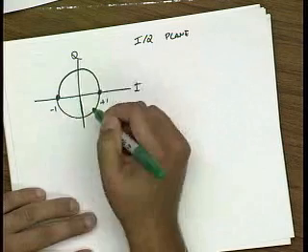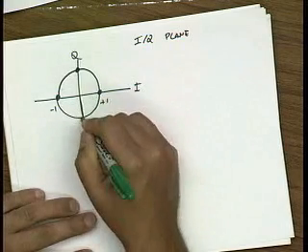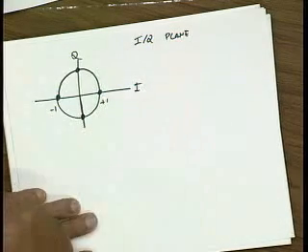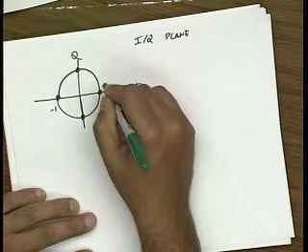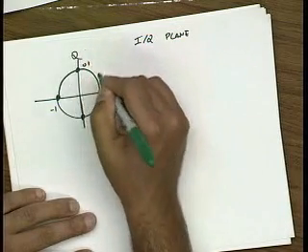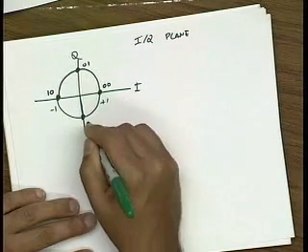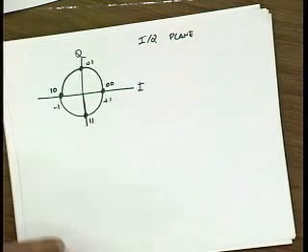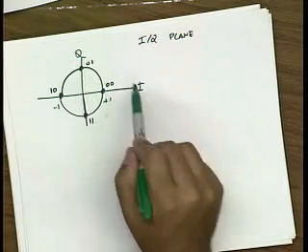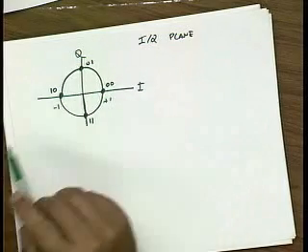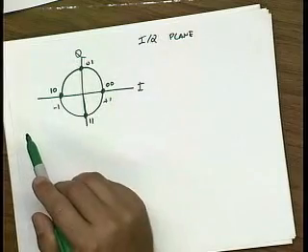If I want to pack more information, I could actually pick 4 points and send these 4 points, basically encode my data. So this might be 0, 0, this might be 0, 1, this might be 1, 0, and this would be 1, 1. So in this way, I could basically group 2 bits together and then transmit one of these IQ signals, and that would represent the modulation.